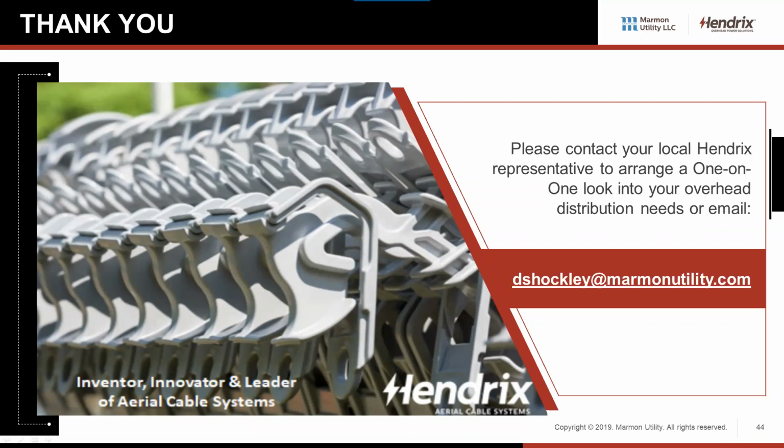Ted, what about the construction aspect of spacer cable, having a messenger as a neutral and acting as a static wire? We have a white paper on this as well, if you'd like more in-depth reading, we can send that to you, but maybe you can address that as well. Yeah, that's something we've thrown out in the past. Since the neutral is grounded and on top of the system, it can really work just like a static wire, like you'd see with transmission.